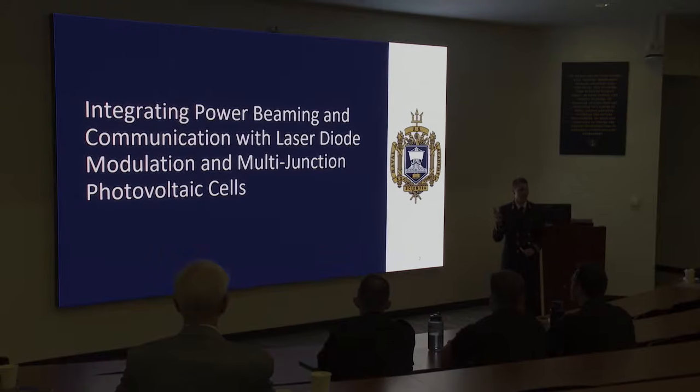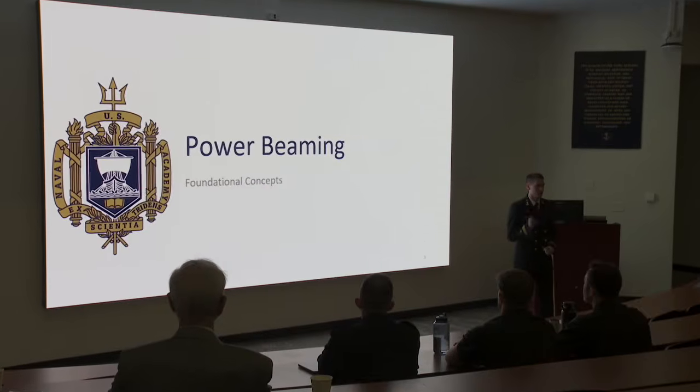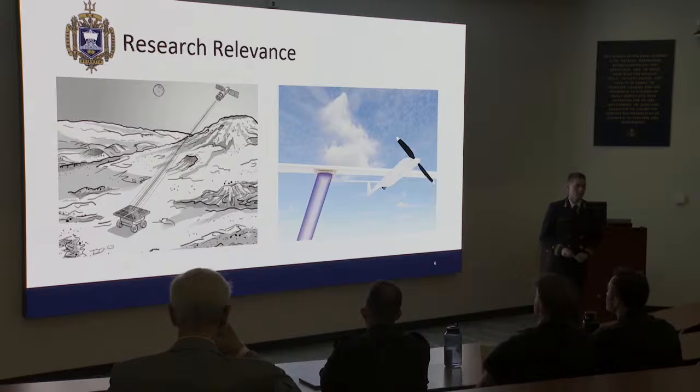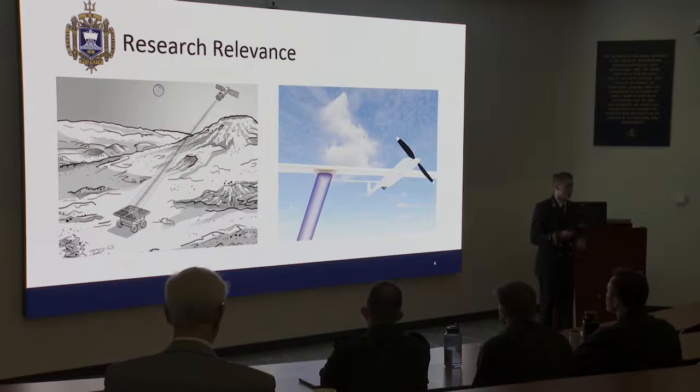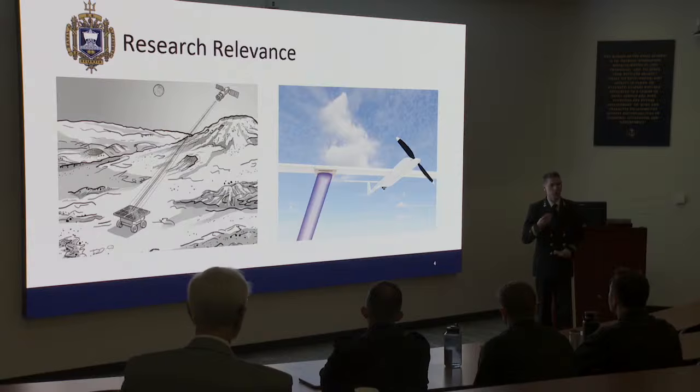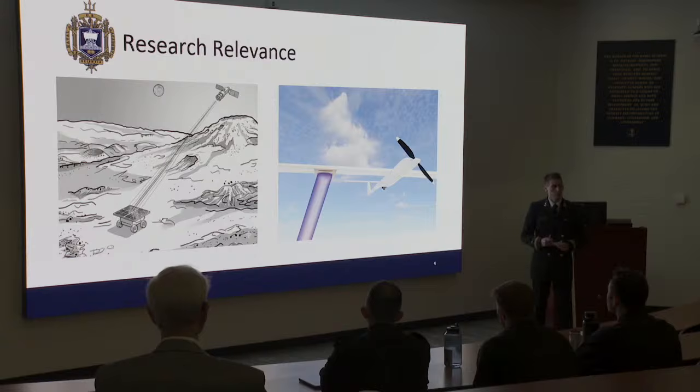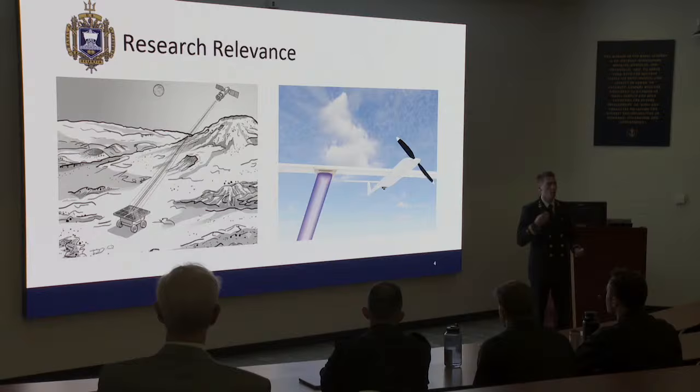Let's start by breaking it down by what I mean by power beaming, and what that actually means for my research. So I'm focusing on laser power transmission, LPT for short. These power beaming technologies function by using lasers, typically laser diodes, to beam power onto solar cells, or photovoltaic cells, PV for short. These systems operate at distances typically from hundreds to thousands of kilometers and have magnitudes of power transmission up to megawatts. These systems essentially allow us to outsource the power generation and storage capability for any kind of electrical system or vehicle, whether that be on the terrestrial or space-based side.